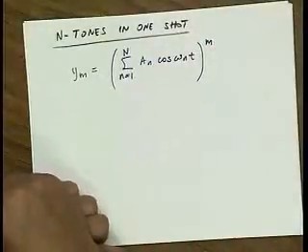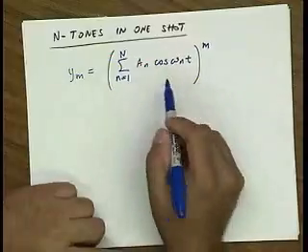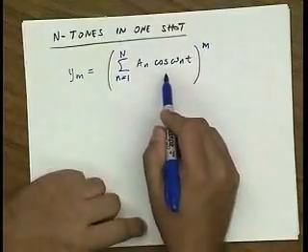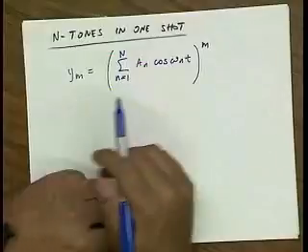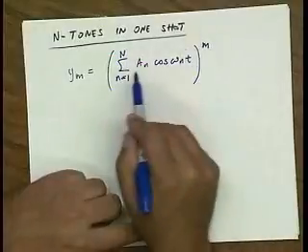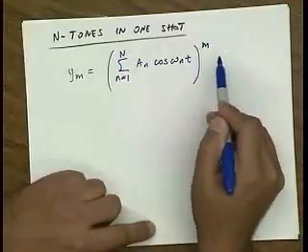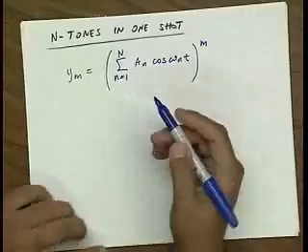We basically want to find out what the amplitude of all the various mixing products are going to be. The special case was we solved the problem of one tone. We did this one special case, and then we did the one tone with a general power, but for two tones, remember, we only looked at second power and third power. Now we're going to solve it in general.